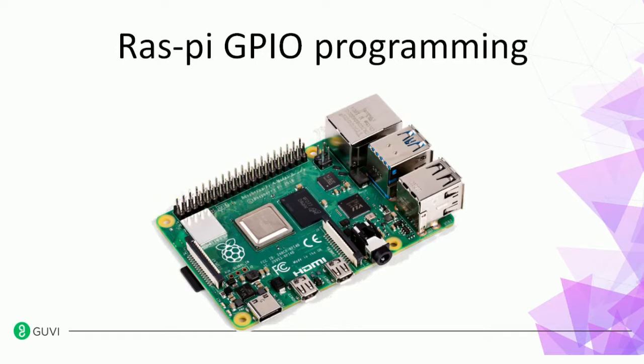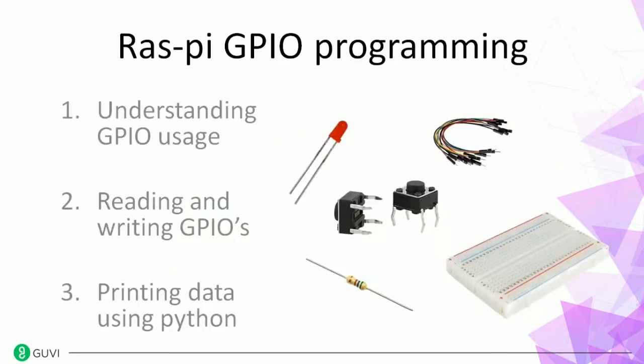We will be actually doing two GPIO programs. One is reading a button state, so this one, and in the next we will read the distance value from an ultrasonic distance measurement sensor. In this episode we will be reading the button state. We'll be using an LED, momentary switch buttons, a resistor, some jumper wires, and a breadboard. The breadboard is needed to build our circuit.